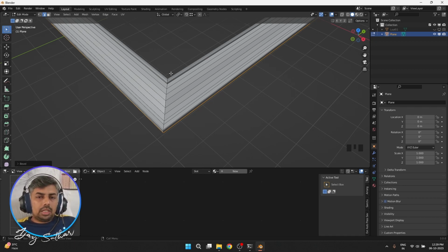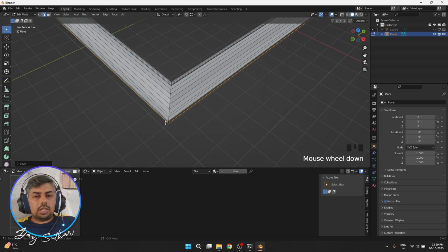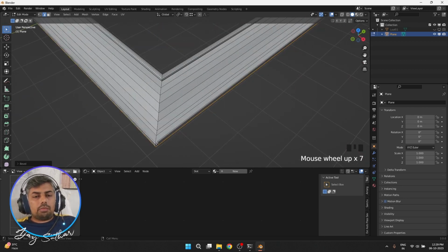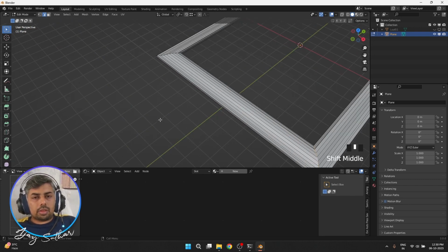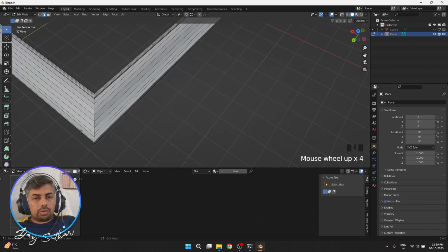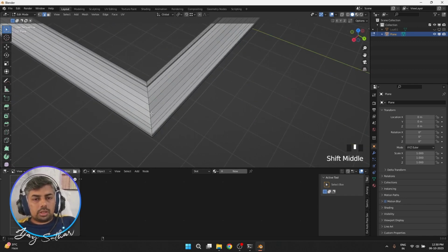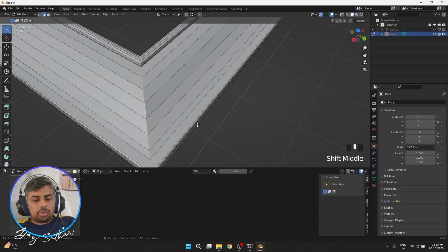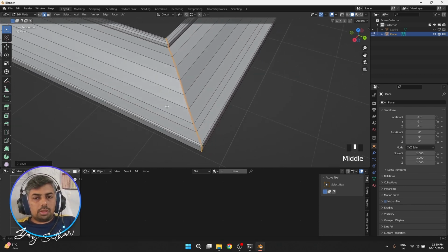But what if we create a groove here to explain that these all are one single stripe, cutting them piece by piece and making it as a frame. If we are creating something by wood, then we should show that. But if your material is not wood, then it's okay if you don't show the joints here. So what I will do, I'll select these, I will also select these, all four corners. Then I'll say Control B and a very small bevel.